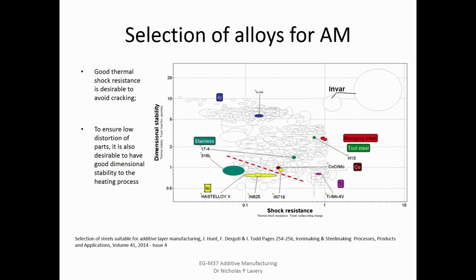So in that kind of area, those are alloys which are easy to process. And then they've got some further up, so tool steels, maraging steels, steels which require some sort of heat treatment afterwards to retain the tensile elongation and hardness properties. And they're more difficult. So everything above the line is actually more difficult.